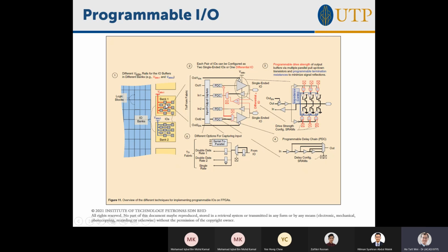The FPGA pins allow you to directly deserialize the bits. Let's say you are receiving SPI bits, 8 bits, but you're receiving them in sequence with a particular clock. To make the logic simpler, the I/O itself can just say, I received these 8 bits, and I just have a parallel 8-bit line. The parallel 8-bit lines then go into the routing logic.